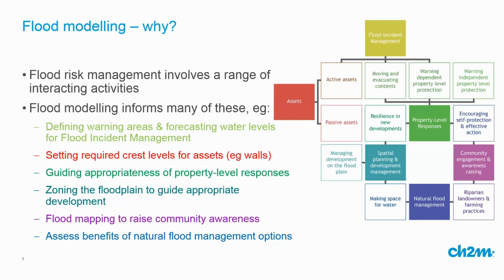So, as I mentioned earlier, flood modelling is a key component of many aspects of flood risk management. The picture on the right-hand side of this screen, these boxes, show the interlinks between various activities in flood risk management. If you look at the coloured-in squares starting at the top, it's flood incident management. Now, this is the process of the things that are done immediately prior to or during flood events, such as issuing warnings or cleaning trash screens or this type of thing.